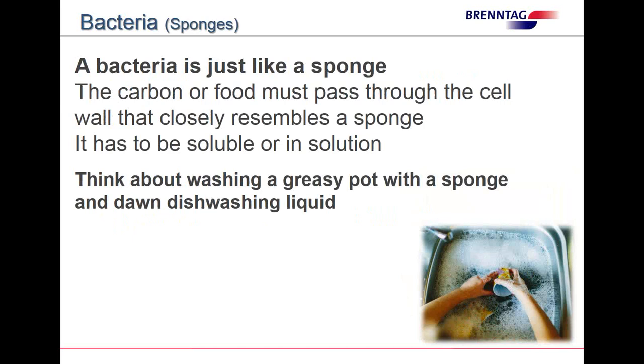Okay, so let's talk about a bacteria. A bacteria is just like a sponge. If you look at it, the carbon or food, the BOD constituent, must pass through that cell wall that closely resembles a sponge. That means it has to be soluble and in solution, or else it's not going to go. Bacteria don't have teeth, and they don't chew on things. They absorb things. And the only way they absorb is if the constituent is completely soluble in the water.